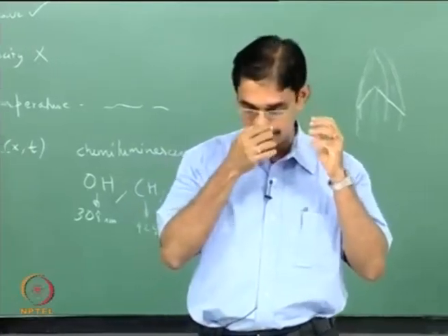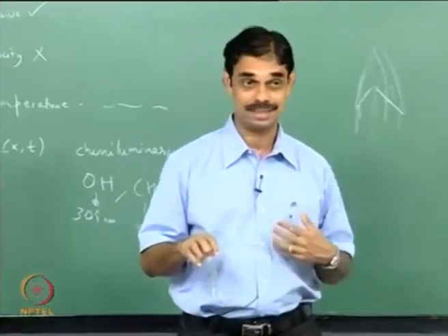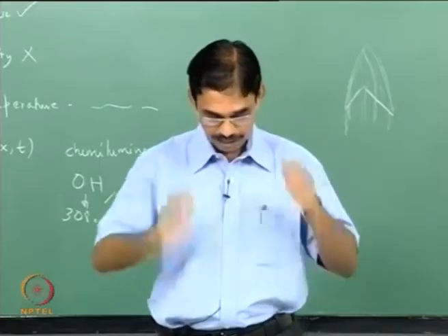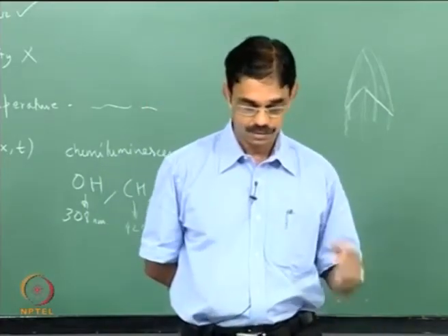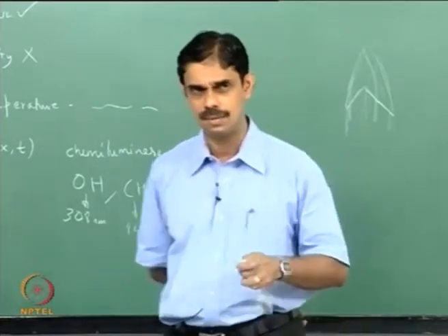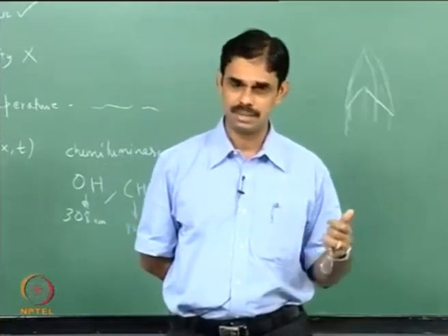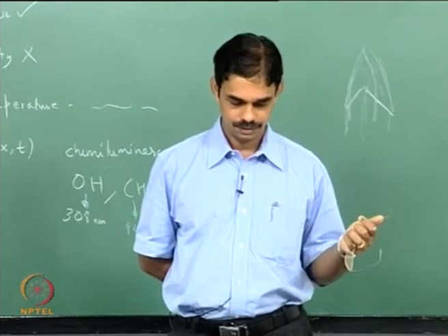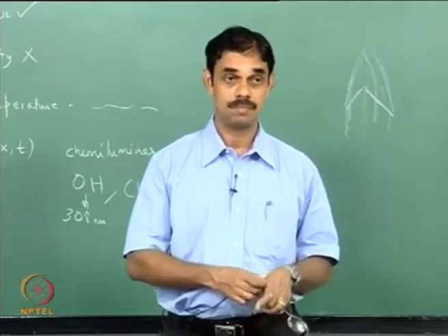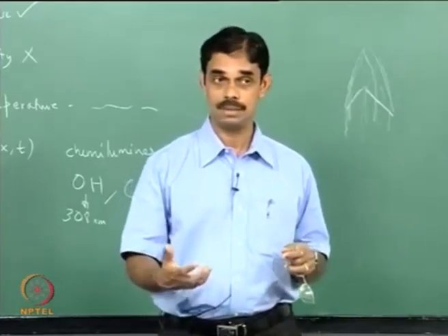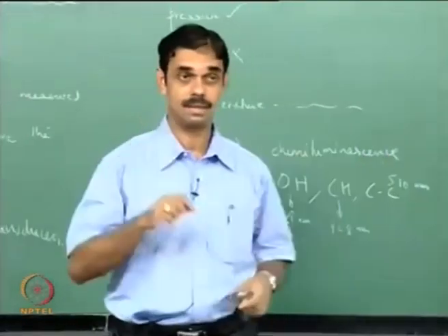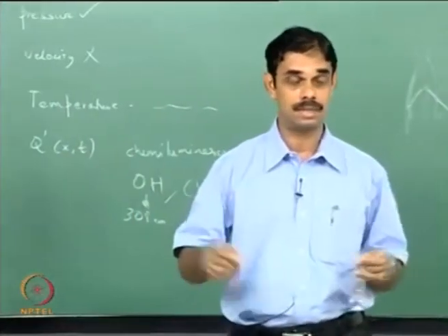So we speak about actuators, which are a major irritant in this active control, because like I said, engineers don't believe that these things can work for so long. Satisfactory actuation of combustion systems presents a real challenge, because you have to operate these actuators under high temperature. If you look at the history of combustion instability control, first the anti-sound concept came, that is the active control of sound by sending sound out of phase with the incoming acoustic field. That's like the speakers from Bose, which will cancel the aircraft noise or train noise and so on.